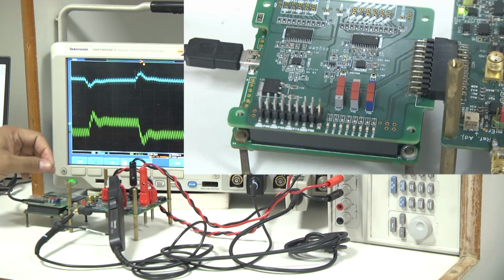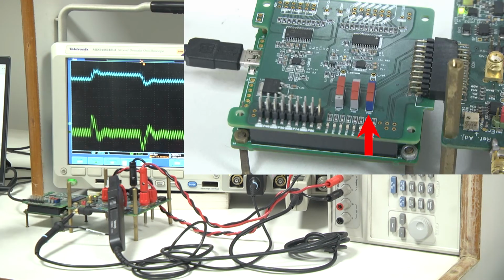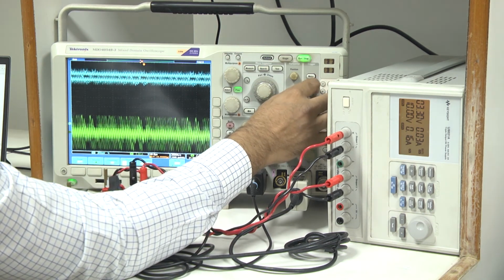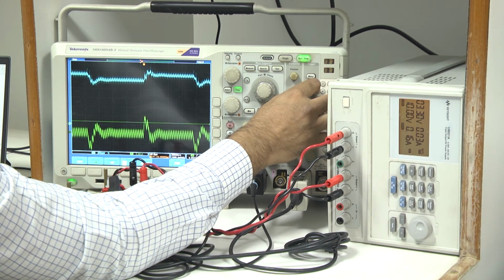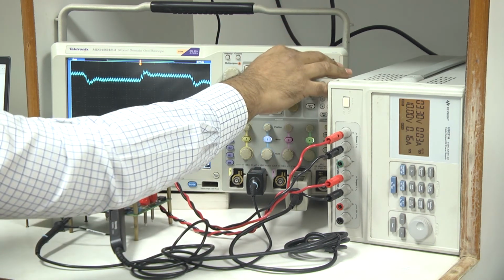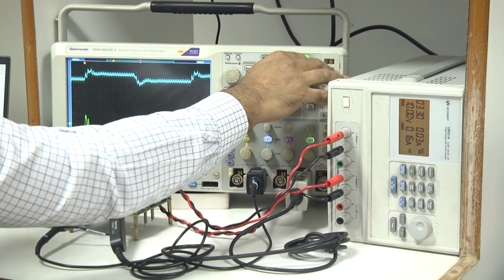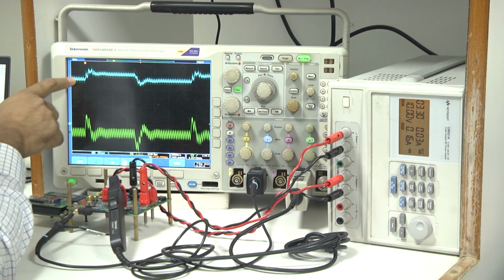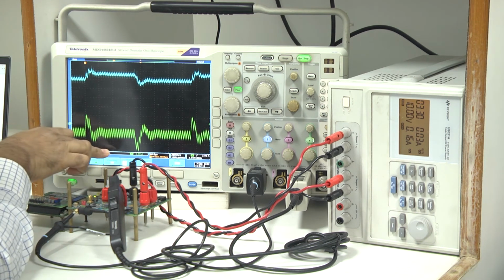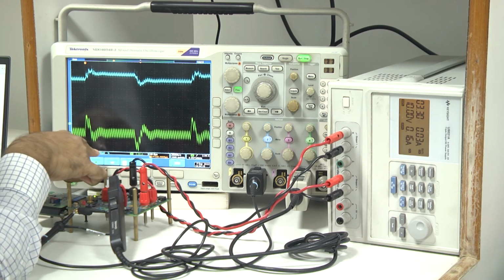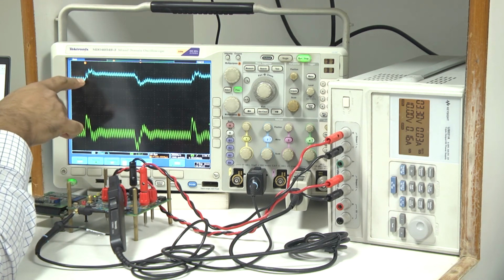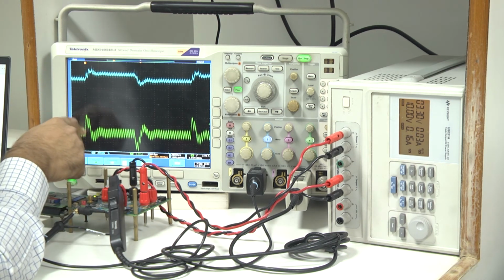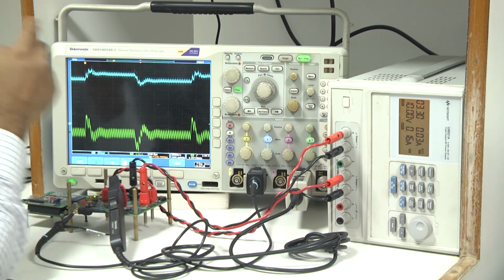Now, we have a switch provision we have discussed. If you change this switch position, it makes a reference transient. In the reference transient, if you trigger it, I want to show that first it is going to step up the reference, changing from 1 volt. One division is 0.2 volt, so you can see 1 volt to 1.1 volt step up transient, followed by the step down transient. This is the current overshoot during step up and current undershoot during step down transient.